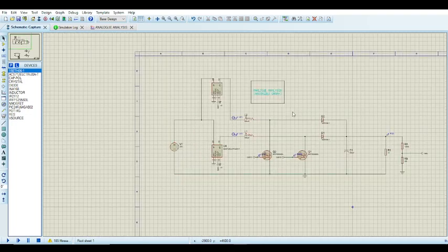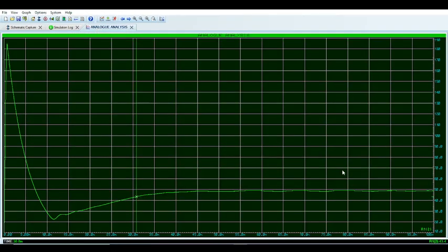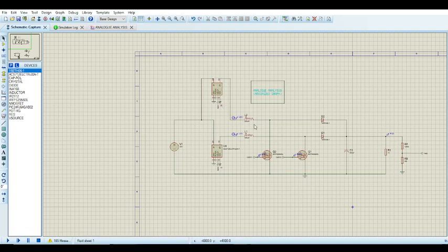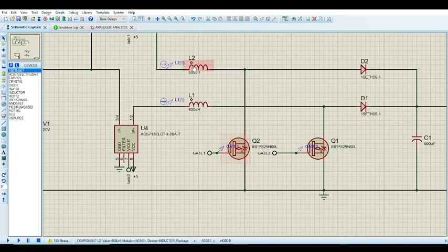It takes a bit more care than just regular control, like just voltage mode or current mode control. You have to take more care with it, but it's rewarding. I mean, look at this. I know this is not perfect, but if you compare this to voltage mode control and take a look at the current going through the inductor, it's ridiculous. The current going through the inductor is also going through your MOSFET, so your converter is probably not going to last that long with straight up voltage mode or straight up current mode control.